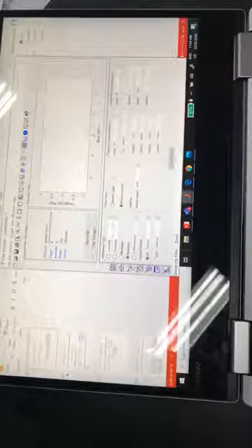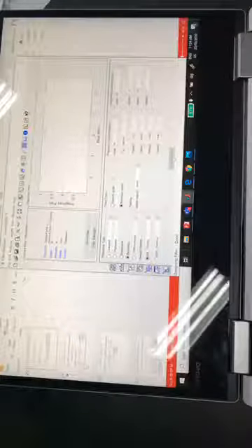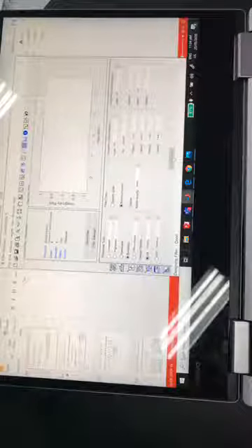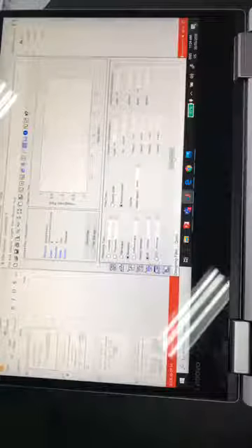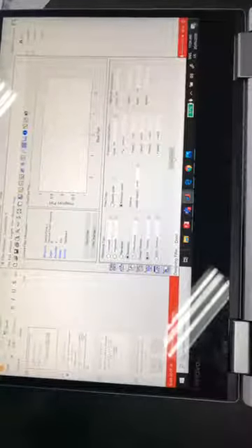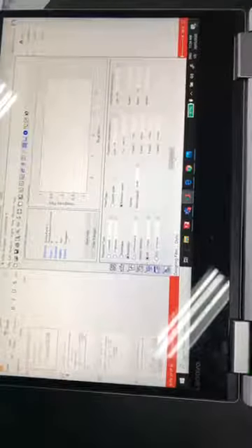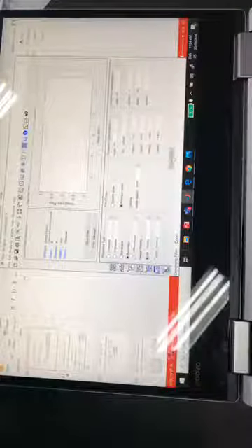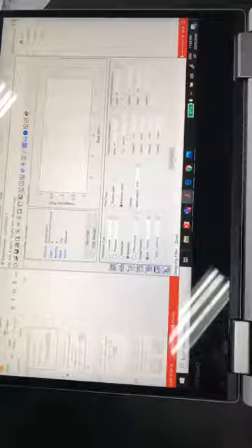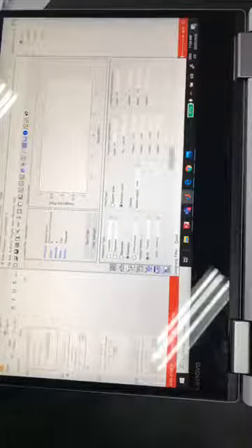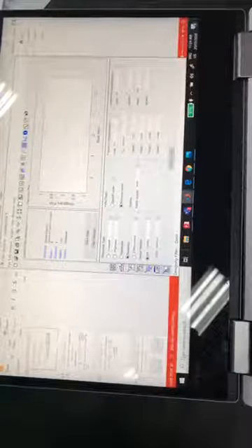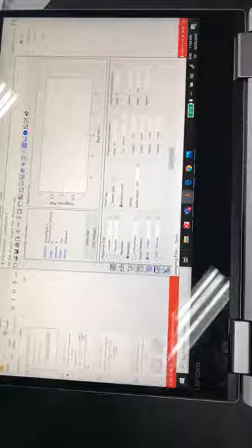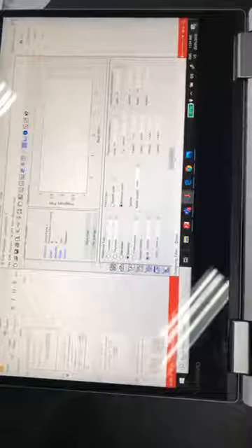So zeros are placed on the unit circle to stop frequencies, and in IIR filter there are poles in complex conjugate pairs, the frequency which you want to pass. And in linear phase FIR filter, there are clusters of 4 zeros in the frequencies which you want to let pass. There exist clusters of zeros,